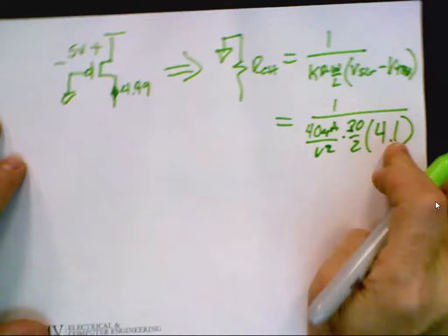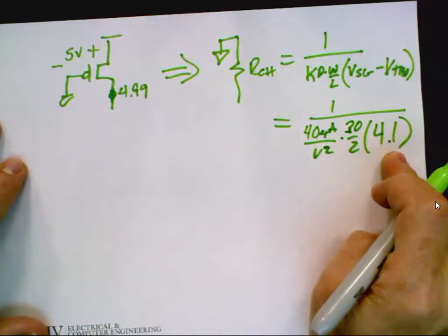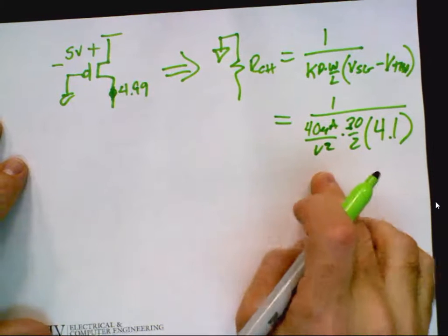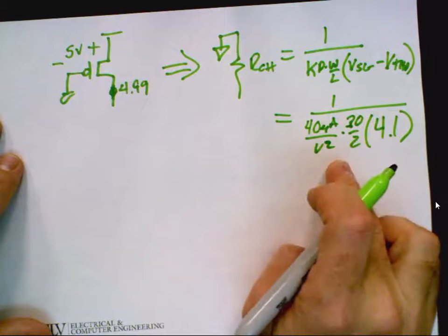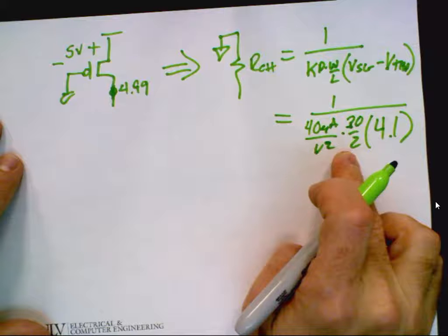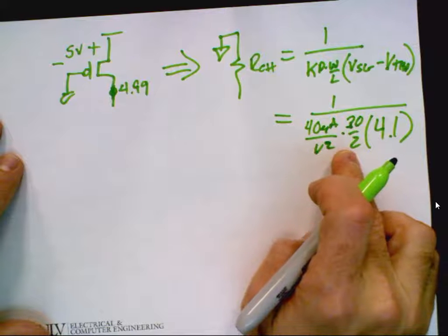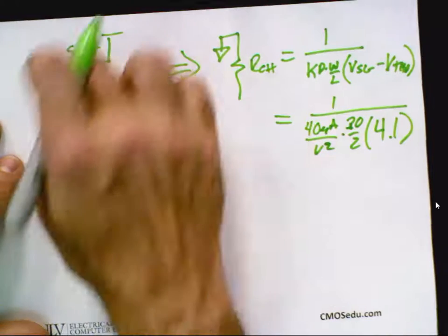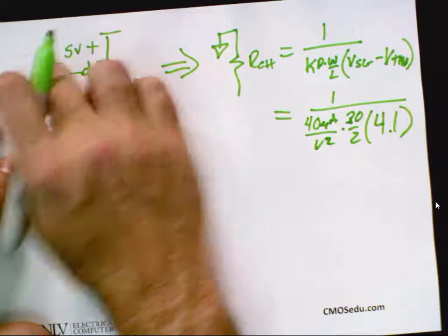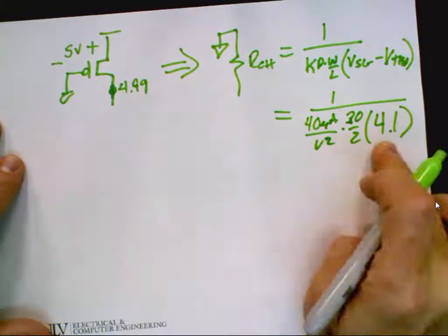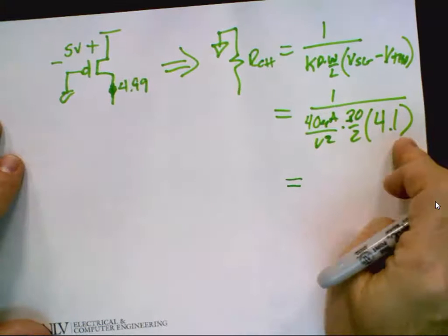Here's where a lot of times students will make mistakes, because if you look at the schematic, all the NMOSs have 1.05 volt VGS, and the PMOS has a 1.15 volt VSG. So here, you're physically holding it to 5, so it's a little tricky.